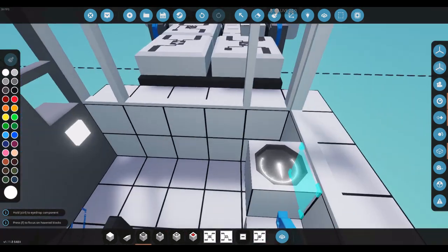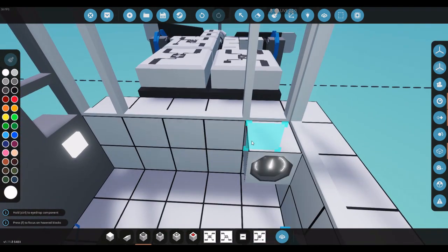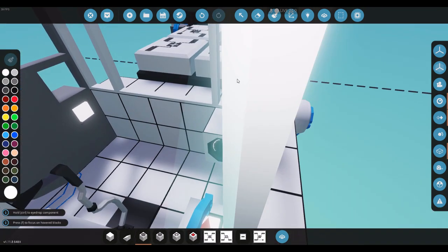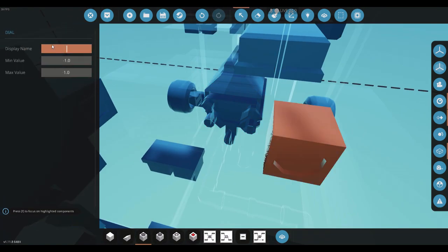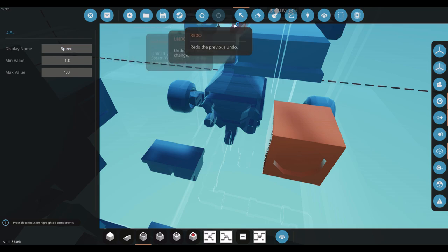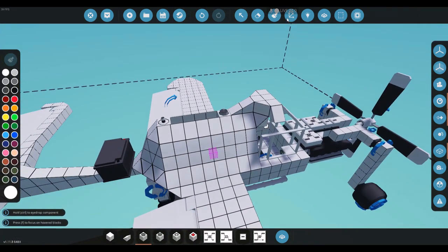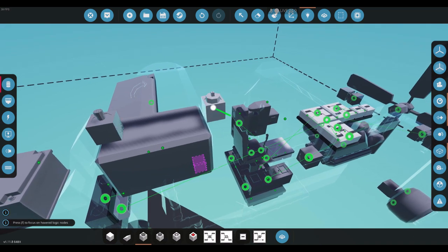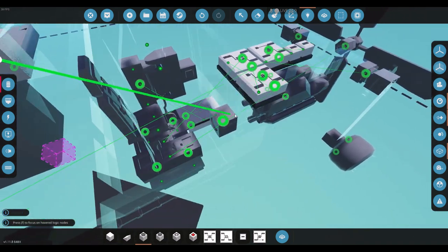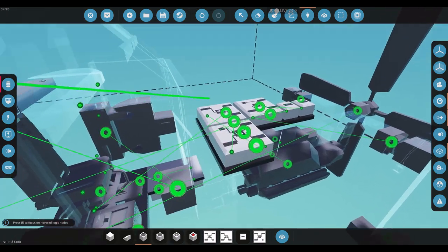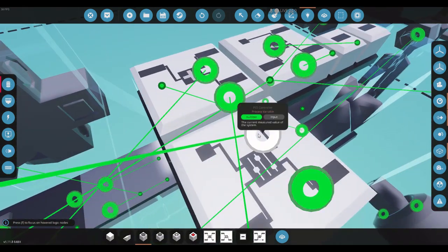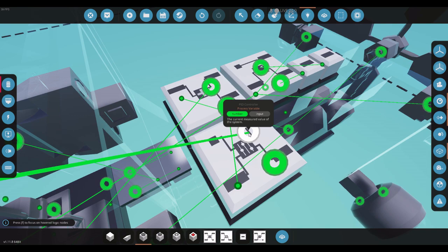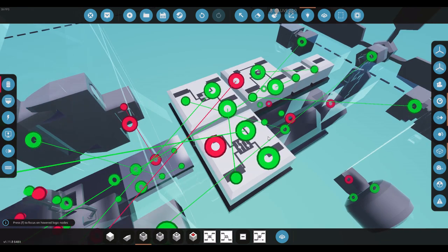So we have the speed sensor, and now we're going to hook up the dial that'll have our speed. And so here we will write speed. So speed is going to get hooked up. Now this linear speed sensor is going to be hooked up to two places. We're going to put it into our dial for our speed reading, and then the PID you placed for your speed hold, you're going to put that down to your process variable.